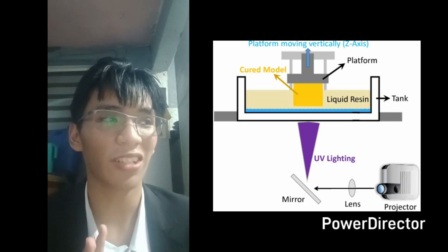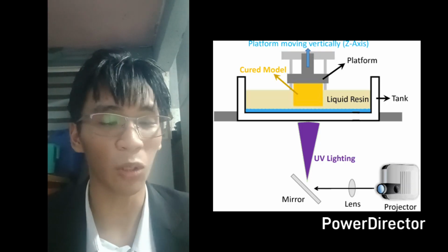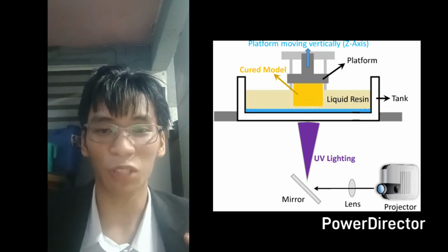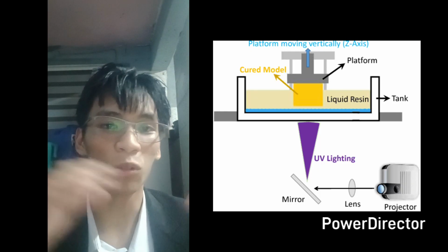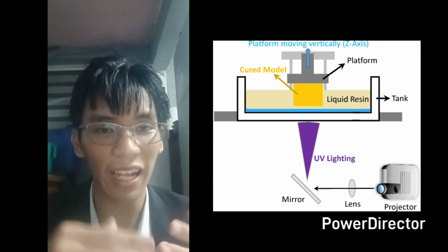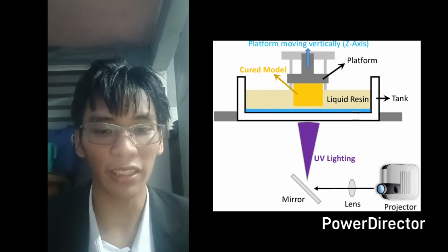That's a lot of words and complexities behind those sentences, but what it simply means is the chemical which reacts with the UV light allows it to harden during the chemical process. And then each time, layer by layer, this process is repeated over and over until the whole object is fully finished. Even slight tweaks to the photoinitiator concentration can drastically alter a lot of factors during the process, such as curing time or hardening time, print resolution, and the final mechanical properties and characteristics of the object.